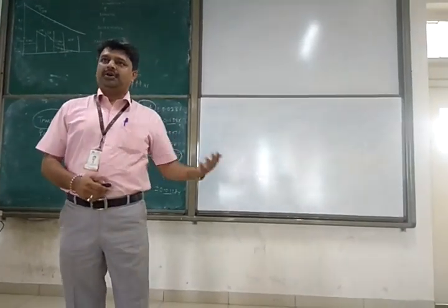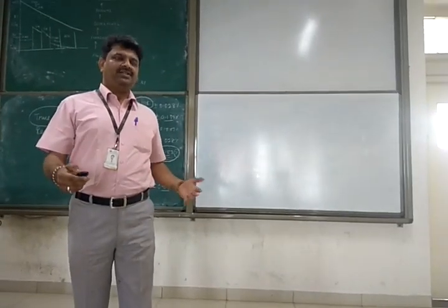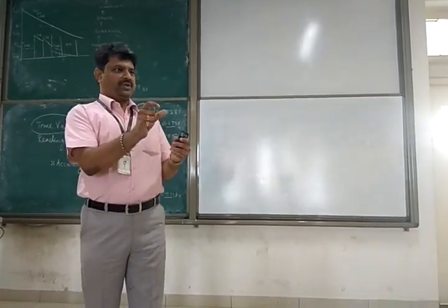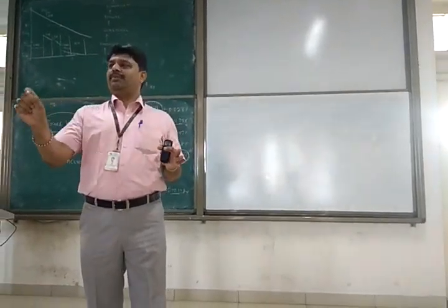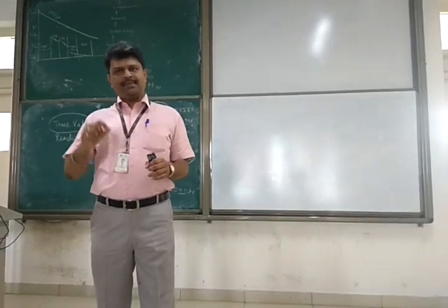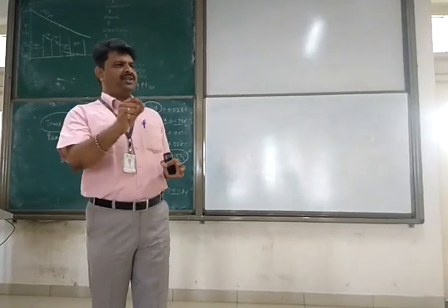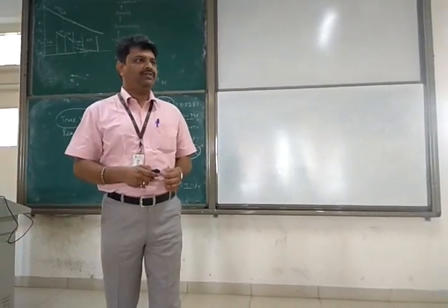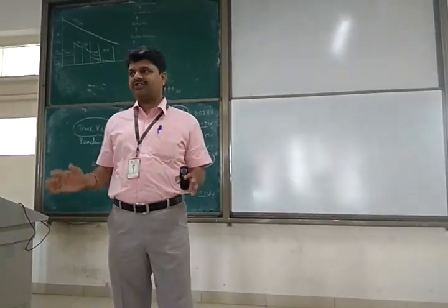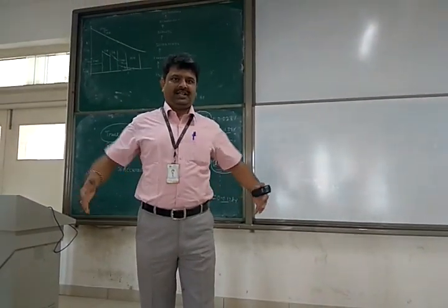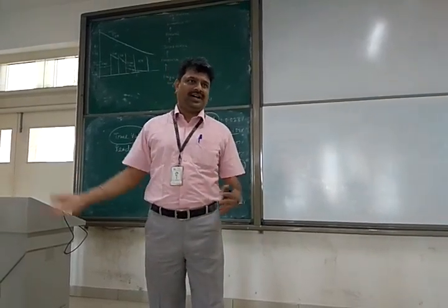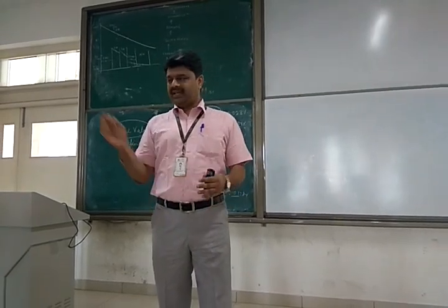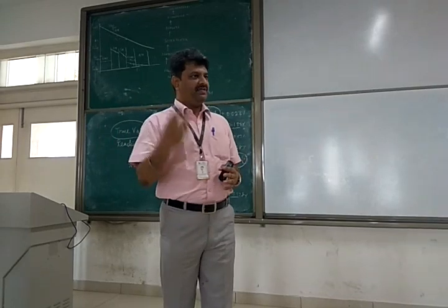I am designing some mechanical instruments. In the modeling software, you might have used some dimension, 25 mm or 25.32 mm, whatever. Is it possible to manufacture the exact dimension that you have designed in your CAD model? It's not possible. There are manufacturing variations because of the machine's incapability to produce the exact size. So we know if I use this manufacturing process, this much variation will be there.